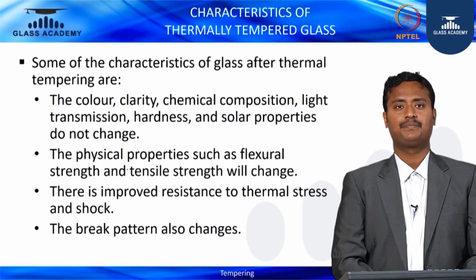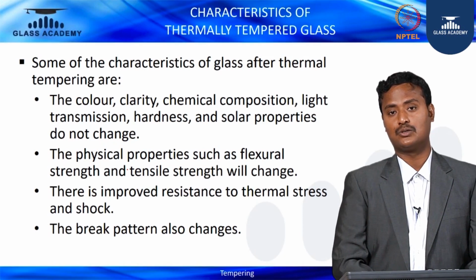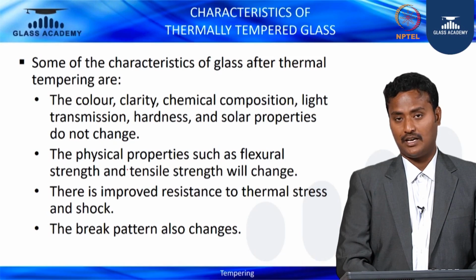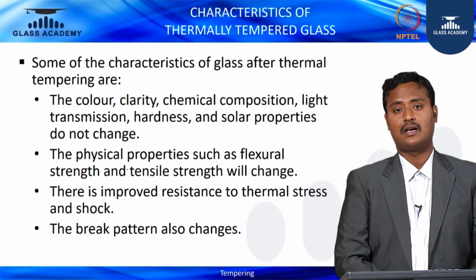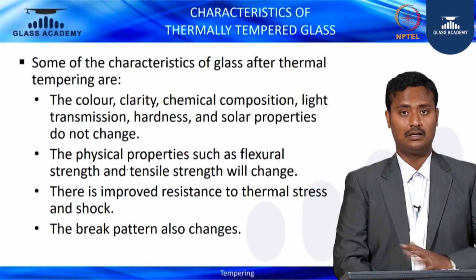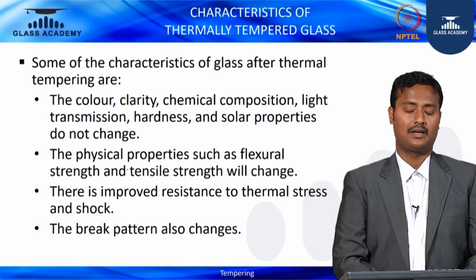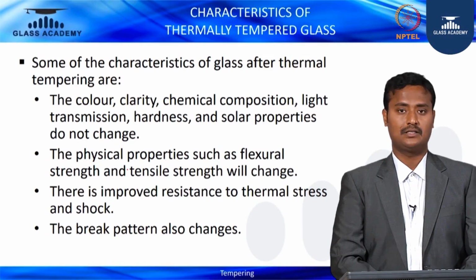The breakage pattern also changes. Yes, obviously this would change the breakage pattern as well. Annealed glass has sharp edges. It will hurt the human beings who work near the working areas. Whereas when tempered glass breaks, it won't hurt anybody because it has dull edges.